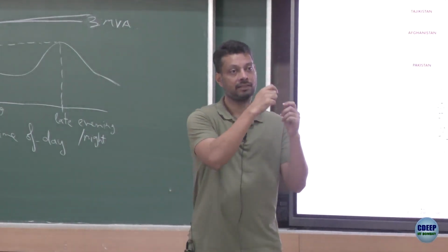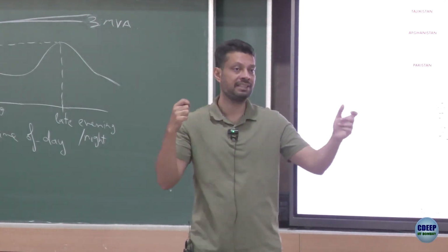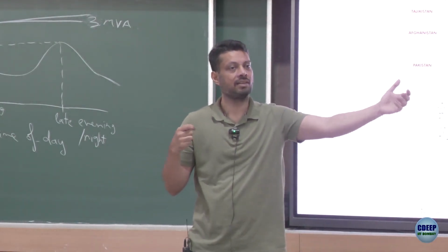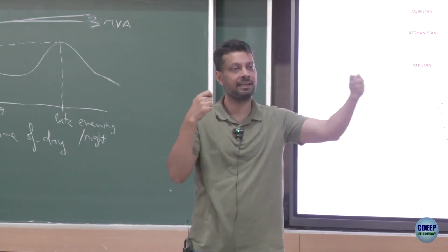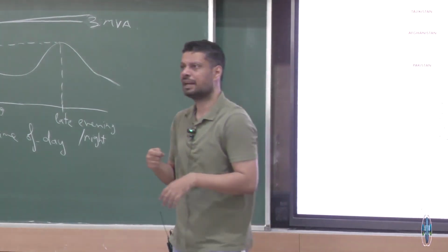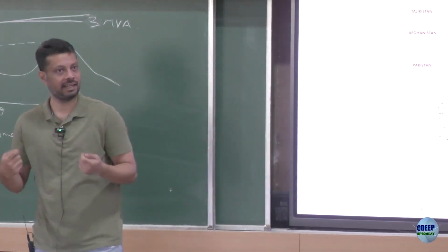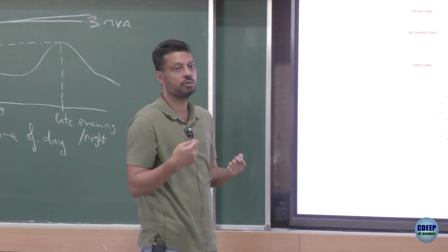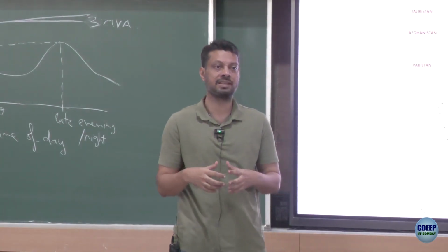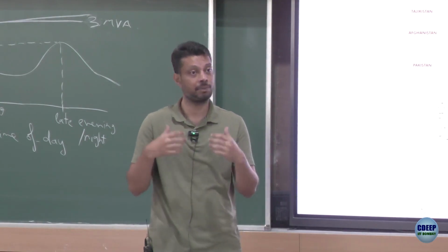It makes sense not to have any synchronous link because anyways there are no loads there. It's only pure generation. So, you can have a DC link connecting that offshore farm with the mainland, right? But as far as my understanding is, in India, all the generation and all the loads are connected through synchronous links. There may be parallel asynchronous links or high voltage DC transmission happening as well.